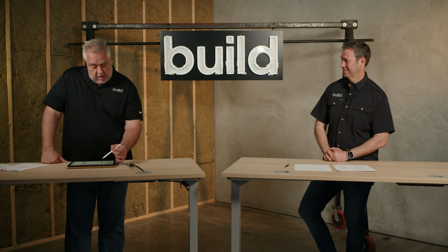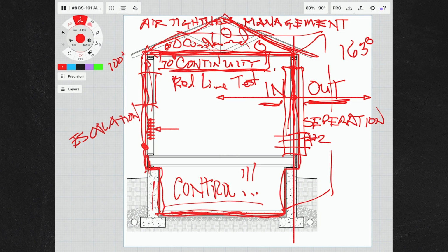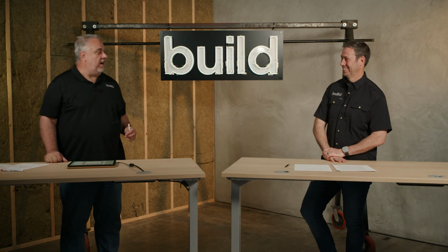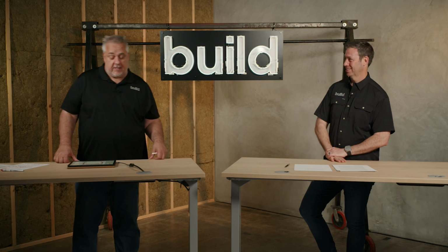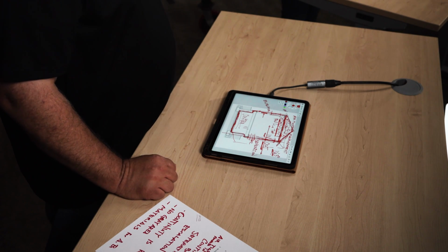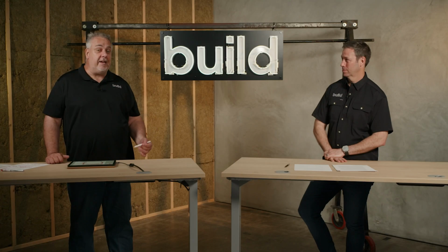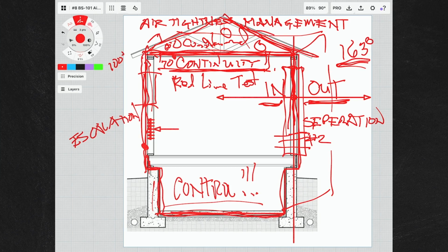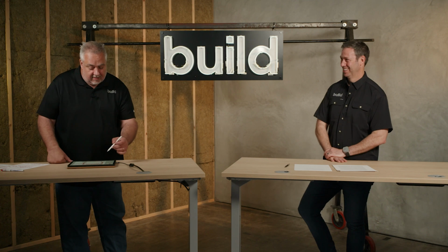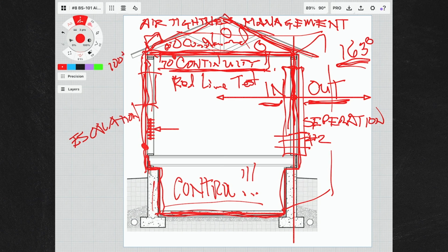Okay? I told you to sit down. Think of the math here. That air is going down a duct at 60 degrees. It's 163 degrees in that attic. It's not just outside, it's actually worse than outside. So this is the part where I pushed the conversation. I looked at the builder and I said, not only is putting your ductwork in the attic in Texas just a dumb idea, you should have run the ductwork on the outside of your roof. It would have been more energy efficient. That's true. By 60 degrees. Yeah. I would have knocked the delta down to 40 degrees from 100 degrees.